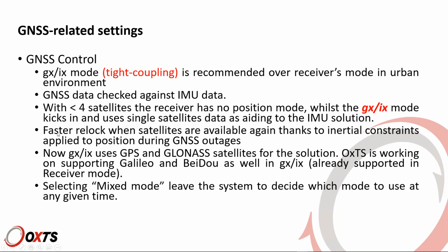Another important aspect is the relock when satellites are available. So if the receiver has fewer than 4 satellites available, it will have no solution. And then as soon as the 4th satellite comes along, it will recalculate its position again based on this available data. That is what we call relock. It takes time. It can take quite a number of seconds to do that. So even if you have those 4 satellites available, you won't have your position back immediately because the receiver will have to start from scratch calculating its position.